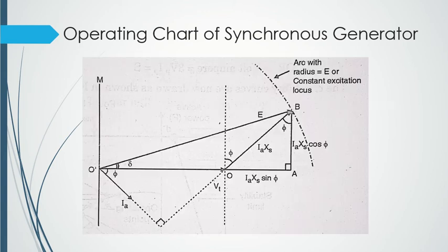Now let's come to the phasor diagram. You can see that in the figure. So if you remember from the previous lecture, what did we do when we were taking the reactance diagram, or plotting the impedance diagram as well, right? We neglected the resistance because its value was too small, because my power factor was in lagging condition. So when my power factor is lagging, my value of resistance will be too small, and because of that we can neglect the IR drops, right?